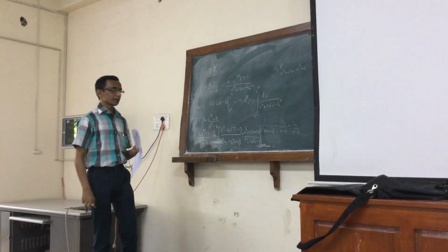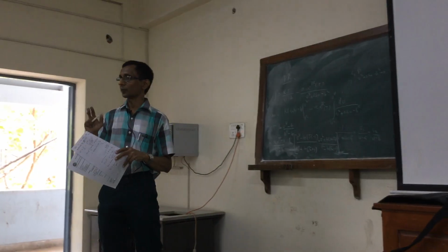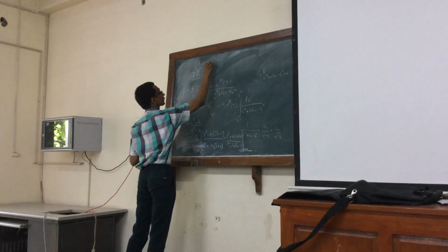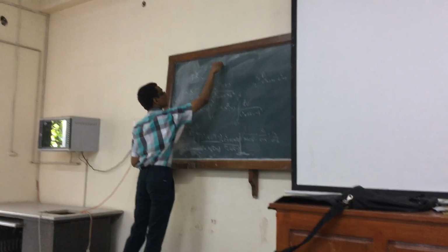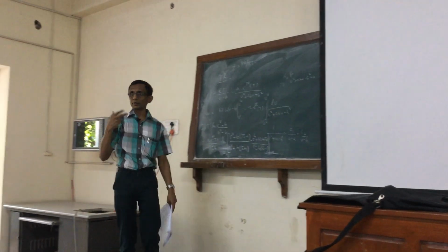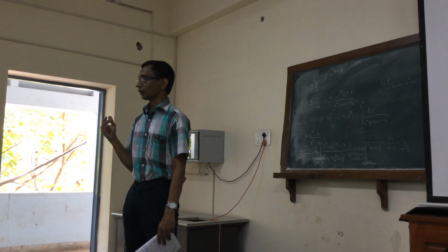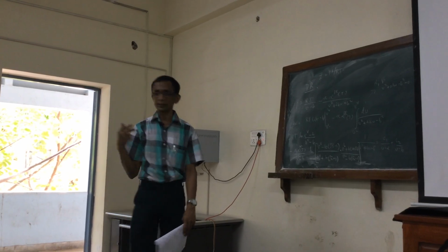Now this is also written in a slightly different form in many books in terms of the compressibility factor, because we know that Z is PV by RT. You are anyway solving in terms of Z, which is recommended, not V. So you get the roots in terms of Z, ZV and ZL.